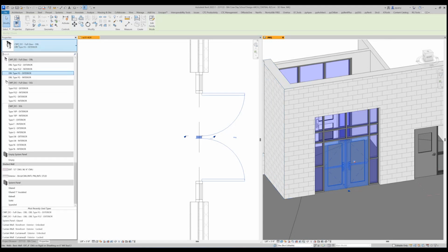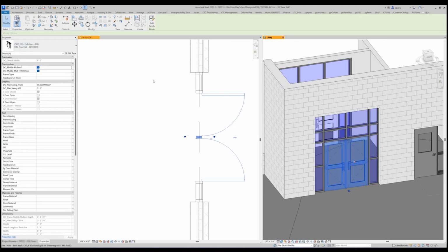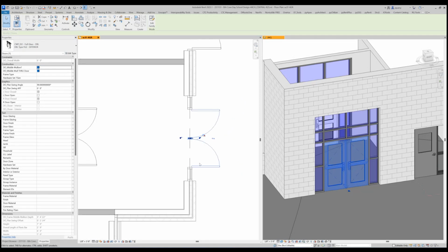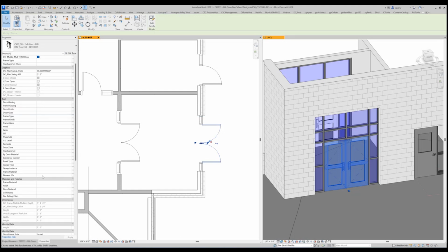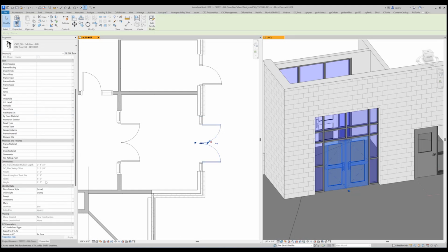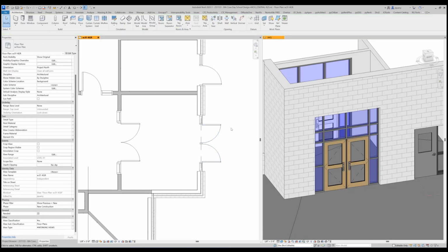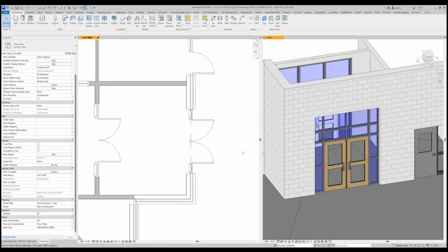So now I can just insert my door into it. This is an exterior, so I'm going to put an exterior FG2 on it. And planned, is it rotate? Is it open the way I want it? Yes, with egress, right? Once I click this, it's the same thing as clicking the panel. I can double check the size at any time. So this 6 foot by 7 foot is exactly what we want. We want 2 3-foot doors here. So that door right there is money. Yeah. Okay. Perfect.